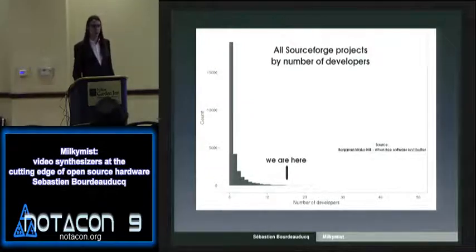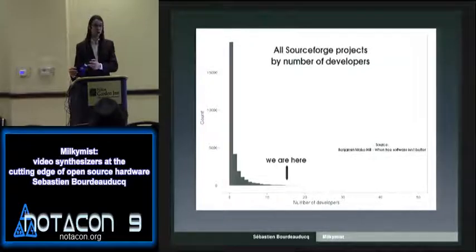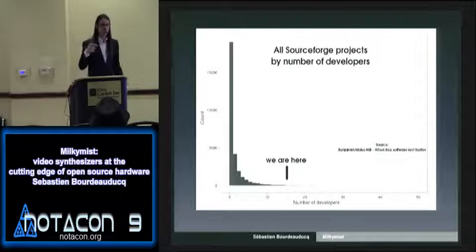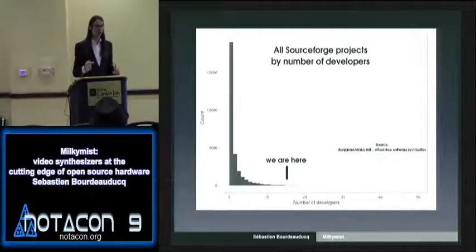Yeah, we have some USB on it. And the USB is entirely controlled by the FPGA. Right now it's USB host ports, and someone is having fun trying to convert that into slave ports. You can do that because you can just program the FPGA and do whatever you want with it. All the USB signal processing is done inside the FPGA. On the PCB you have only analog transceivers to adapt the signal levels, and then all the sampling and the signal generation is done by using the FPGA matrix. So it's a very flexible architecture.